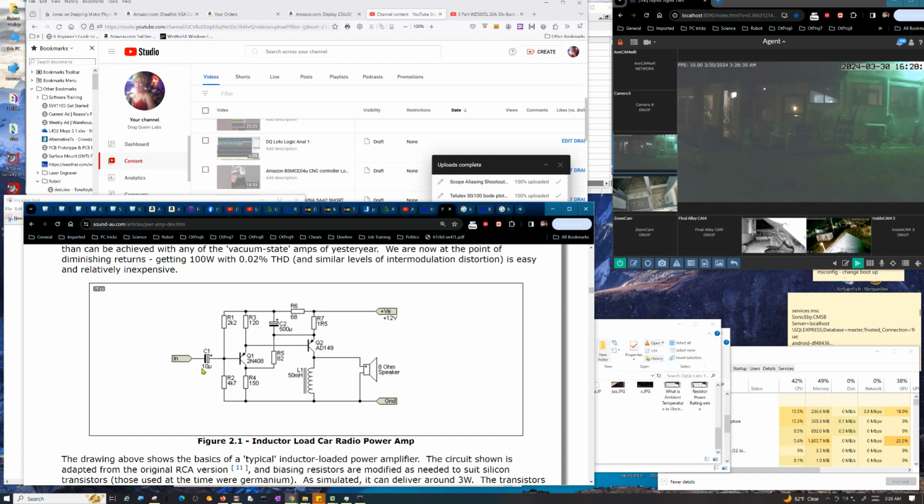So with no signal coming in, this end would have to be less than 8 volts to use the capacitor the way he's got it drawn here. So if it had 4 volts as its quiescent level, in other words, with no signal, it has 4 volts DC across it, or even if it just had 0 volts across it, that's fine, because the polarity's not reversed. It's still positive here and negative here. But you wouldn't want the reverse to be true, because electrolytics in particular act like a short circuit in reverse,